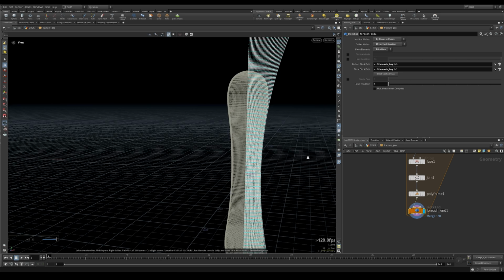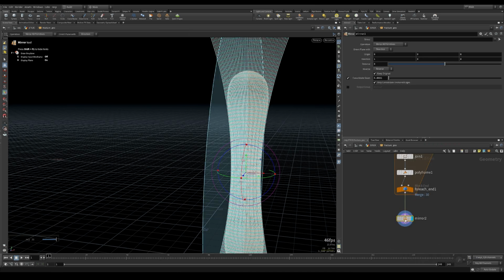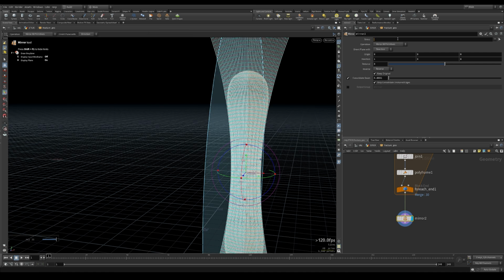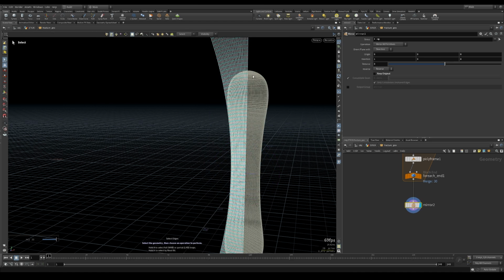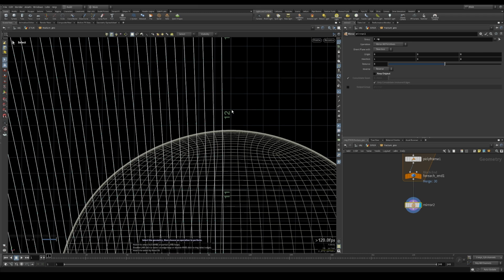So now we have 1/2. Let's create a mirror, and this will mirror on the x-axis, so it is good as it is, but we don't want to duplicate the first curve, because now on the origin we have an overlapping curve, so we should say the group will be everything except the first primitive. So basically, if we don't say keep original and we go in on the front, you will see that we miss the first curve because it's on the original.